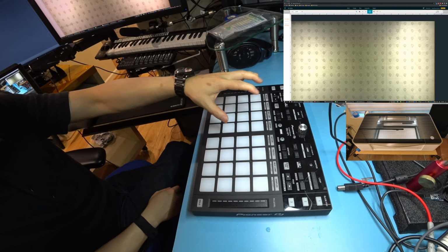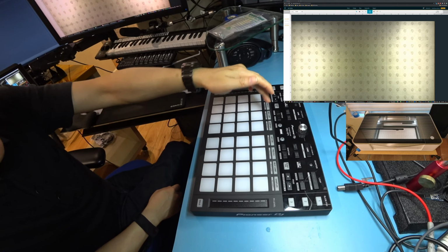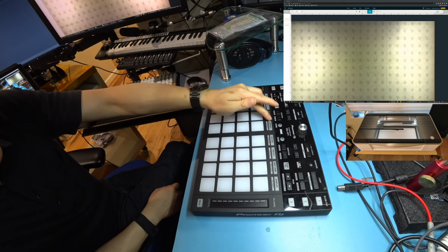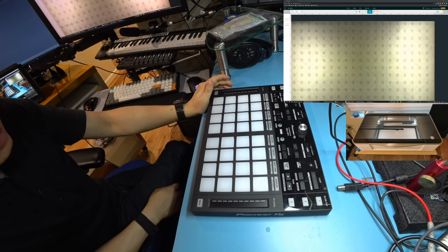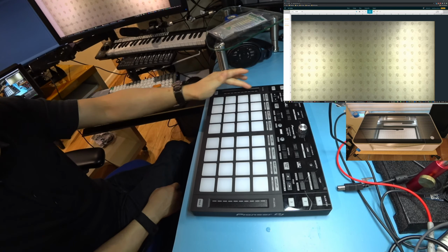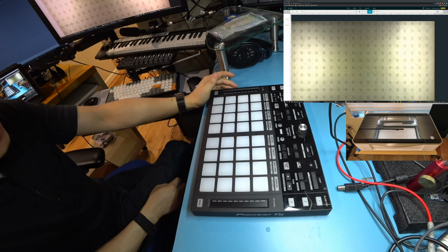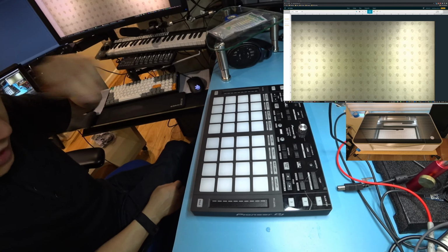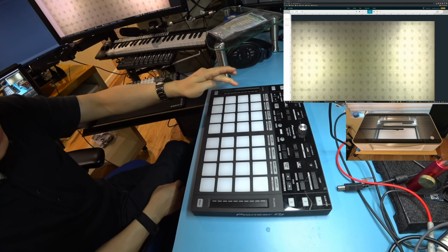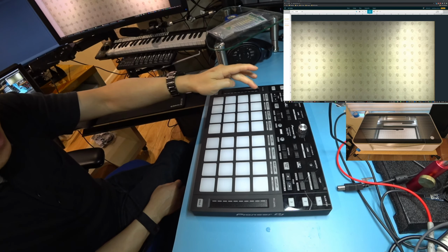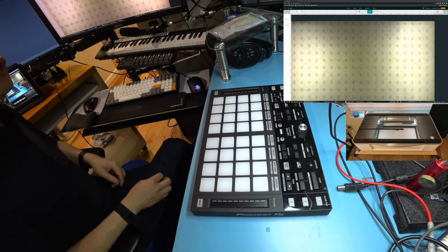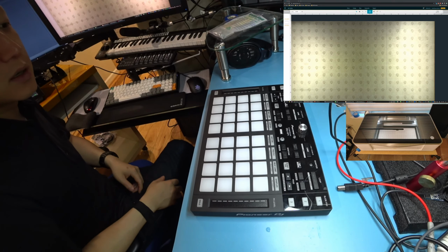And there's memory, or rather, it remembers the lighting setup, because switching banks here is behavior that's in the microcontroller. So if I lit up a bunch of keys, if I switch over to AddFX1, those keys will dim and I'll be in that second group, right? 17 through 32. And when I switch back to hot queue, the first bank from 1 through 16 or 0 through 15, right? The lights will come back on and restore that state. And I don't have to deal with this in code, which is pretty convenient.